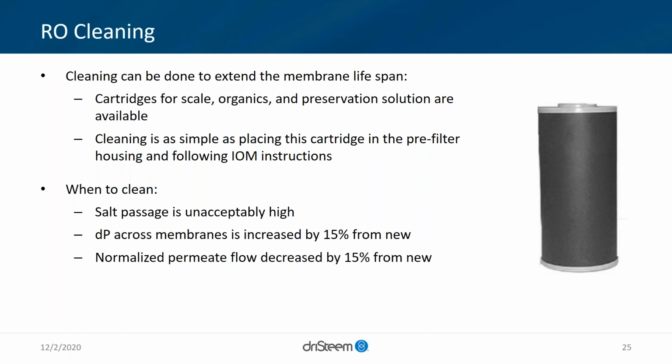Some things to know, well, when do you clean? When your TDS isn't where you need it to be, and it previously was. If the differential pressure across the membrane increases 15% from new, or the permeate flow decreased by 15% over that time.